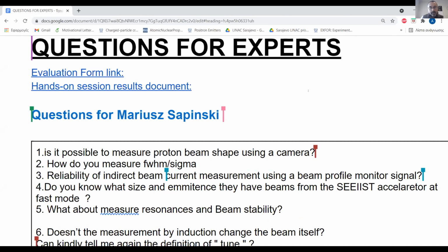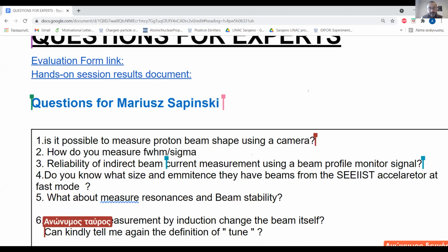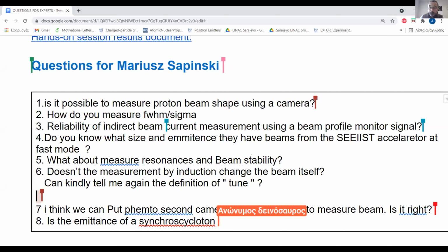You have the ionization chamber and the beam goes through. It's again in the transfer lines, where the beam doesn't come back, because every time it goes through a material, of course, it's affected and it's not a good thing. But we can afford to do it once. So we have this flat ionization chamber, and it works in such a way that the signal is proportional to the beam intensity, and it's very stable. Small changes in pressure, maybe not, but at least in high voltage, do not affect the measurement.